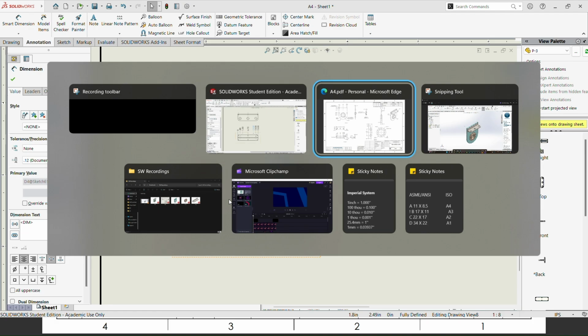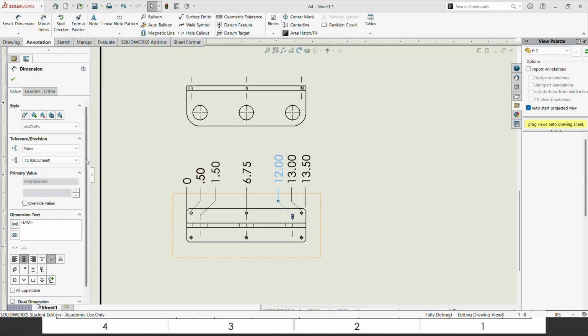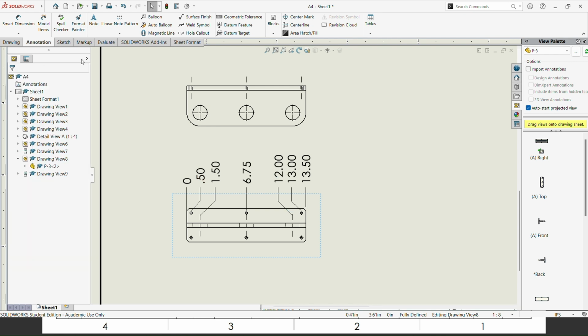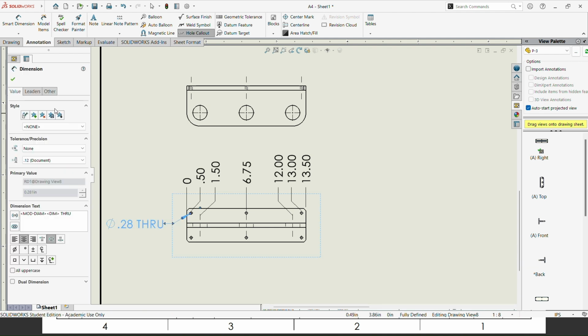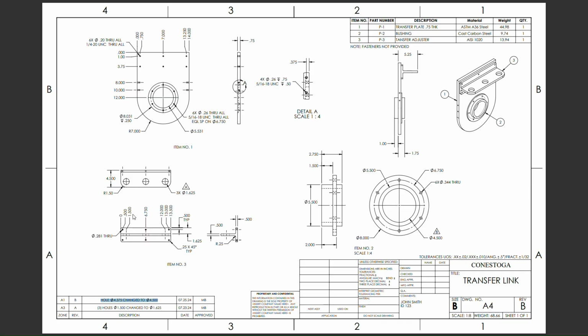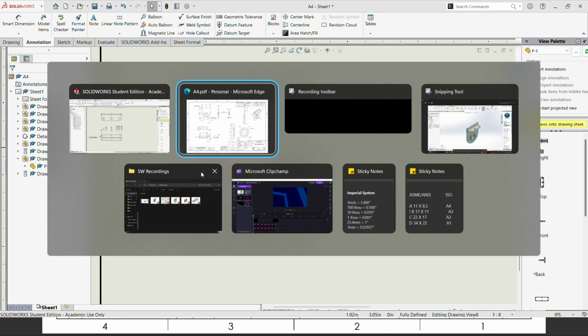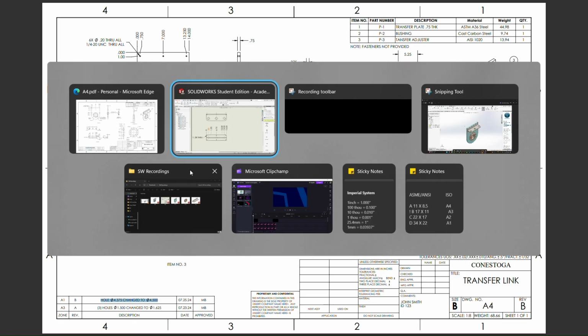Then our next step is, yeah, you can call out this circle or the bold circle. So I'm using the call out function and call out this. Okay, then we can make these dimensions to 3 decimal places, except 0.